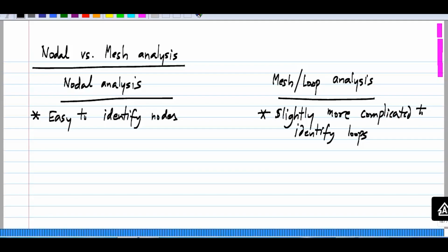Now the other extreme case is you just have one component between these two pairs of nodes, another component, and so on. So your n node circuit consists of only n components, that is, there is a single loop. Obviously in that case loop analysis wins out. You have a single loop and the same current flowing through every component in the loop.